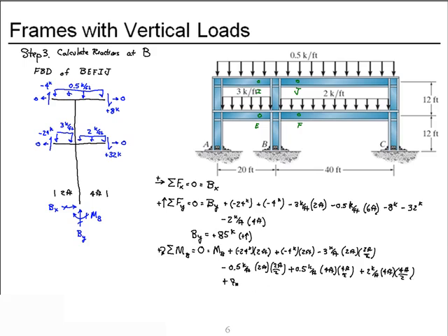And we add the 8 kip shear at J, acting through 4 feet, and the 32 kip shear acting at F through a distance of 4 feet. Wow, that's a lot of stuff acting on our free body diagram. When we put all those together, our moment is a negative 117 foot kips. Remember, we drew it clockwise, so the moment reaction is actually counterclockwise.